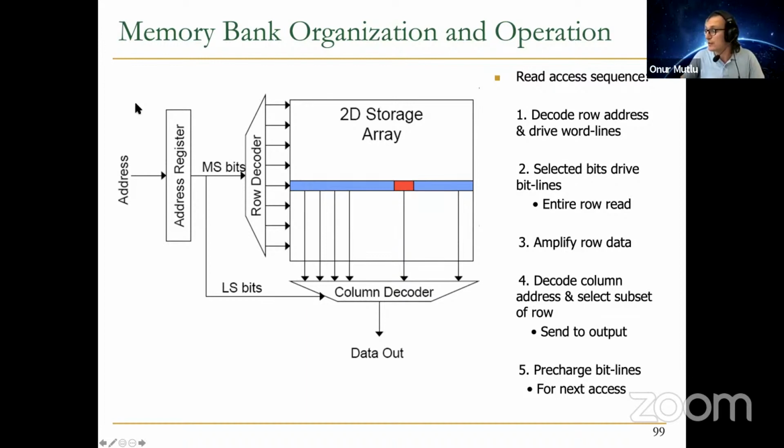So data out is usually 1 byte. It depends, basically. It depends on the DRAM chip. It depends on the SRAM. So in DRAM chips, it could be 1 byte. It could be 16 bits. It could be 32 bits. It could be 4 bits also. There are some DRAM chips that are that way. But in SRAM, it could be actually much more wider, because in SRAM, you normally put SRAM on chip. And on chip, you don't have a pin bandwidth, pin count problem.